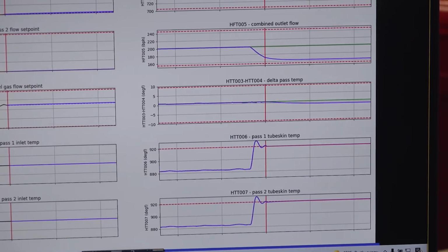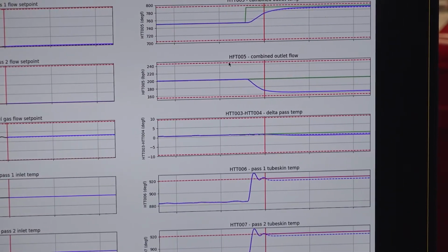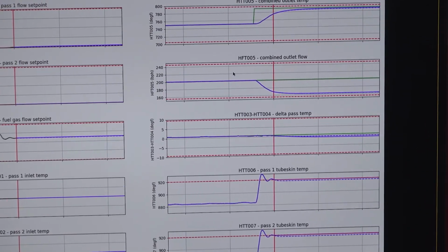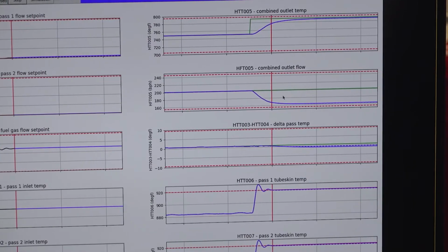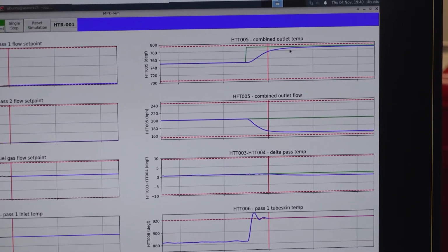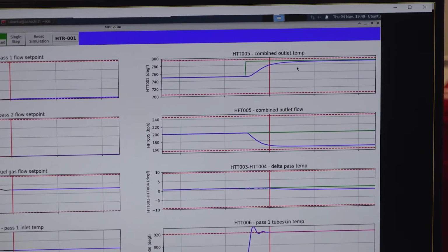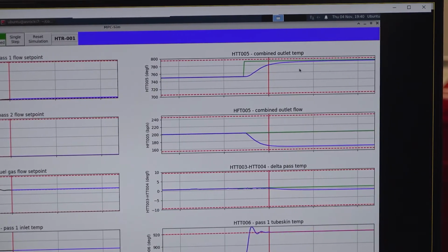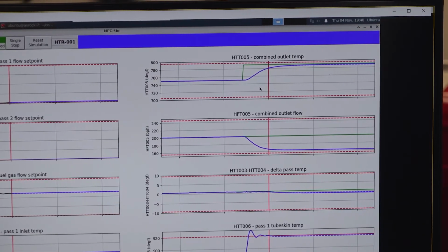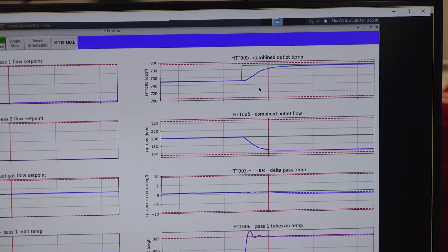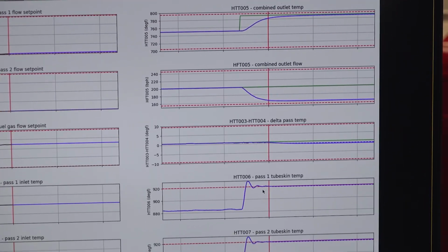And it also says that it's going to bring the outlet temperature up to its set point. And the way it's going to do that is to back feed out of the heater. So we're going to give up on our feed set point so that we can achieve our outlet temperature set point. And that's the priority that we programmed into the controller. And so this is the real value of model predictive control. You can set up priorities. You can respect constraints in a much more effective way.